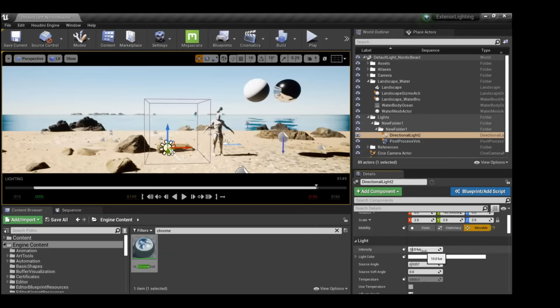Now there is intensity. So basically, for sunlight, if we have used Arnold also, we know that directional light only has the value of 1, which we don't tweak. If we are using V-Ray sun also, we tweak it in the camera settings. So I don't tweak it here. If I want, I can go forward also, I can go backward also. But 10 is a decent amount to get started. If you want an afternoon result also, or a sunrise or sunset, 10 is a decent amount, right? We will go in further also.